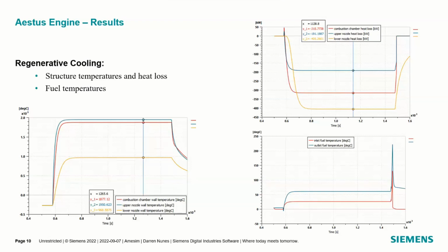We know that most of the heat loss is dissipated through the regenerative circuit. So when the propellant flow stops, right, it's dissipated through radiation rather than conduction through the piping. So we know that the boiling temperature of MMH is 360.65 degrees Celsius at 1 bar. So kind of for the fuel, if we looked at